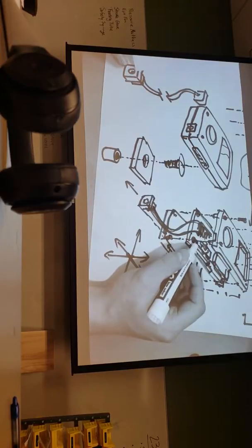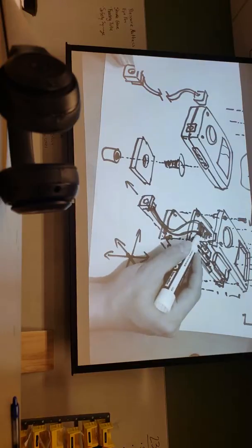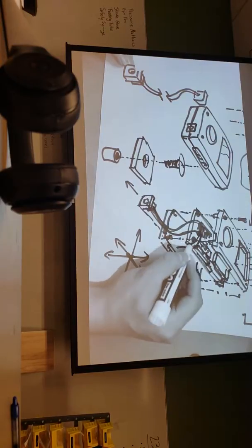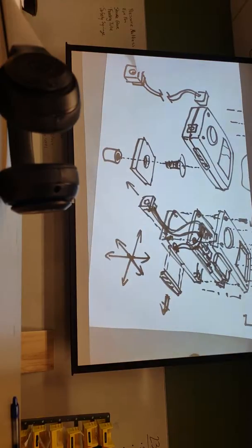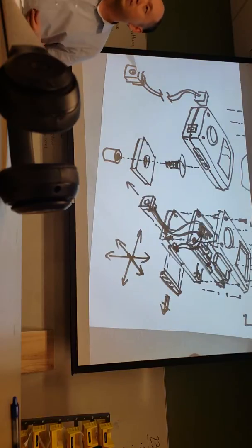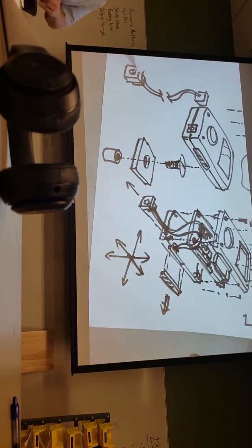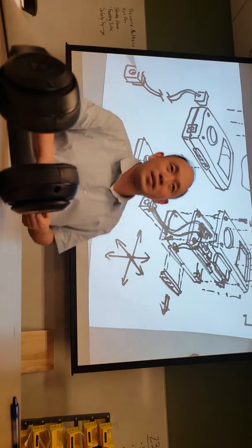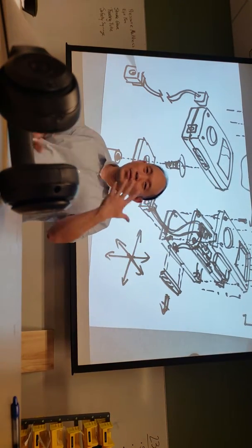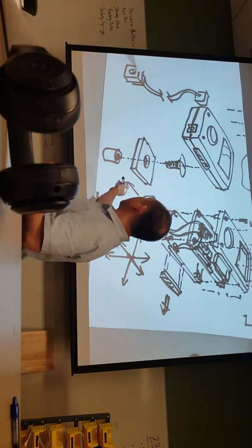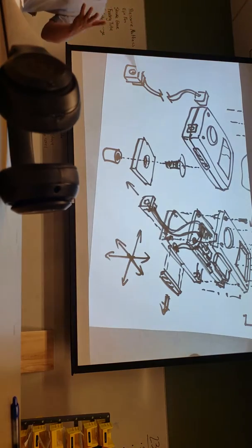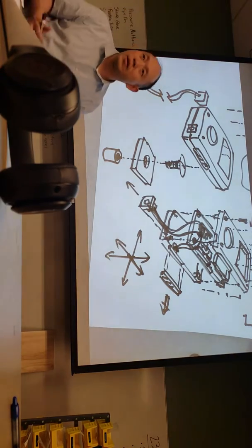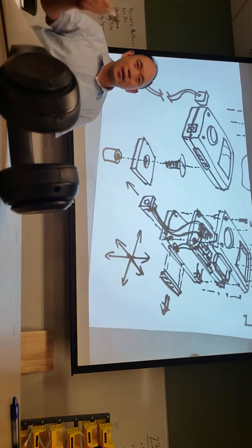With regard to the wire, if it's attached to both, you don't really need leader lines. You can just show that it's attached to this and that it comes down and attaches to whatever's down here. That's why I said you might have to intentionally lengthen the wire just a little bit. Anyway, I don't want to go into too much depth with this, because a lot of you have a very unique way for things to go together. But as long as you're using the leader lines to show parts and you're using the axial explosion method, you should be fairly clear in how things go together. Okay, and I can help you guys with it as you go along.